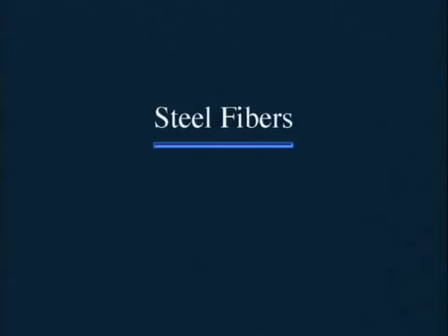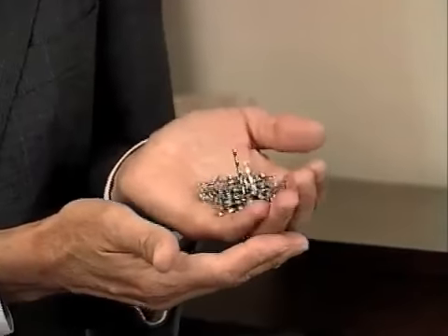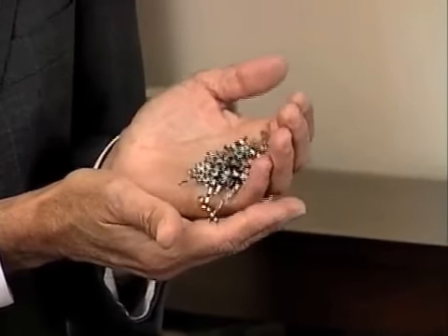Let's move on to steel fiber reinforcement. I really like steel fiber reinforcement. These little fibers are added to the concrete mix, transit mix truck and mixed in with the other concrete ingredients. The concrete is placed and finished using normal procedures.